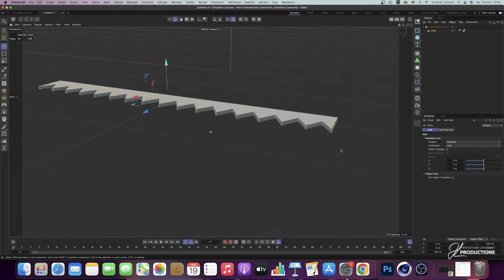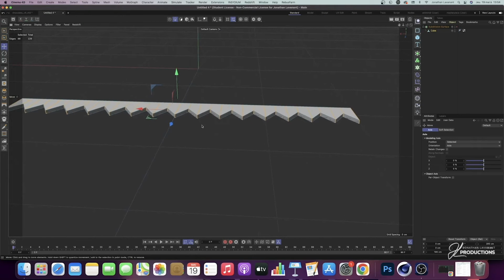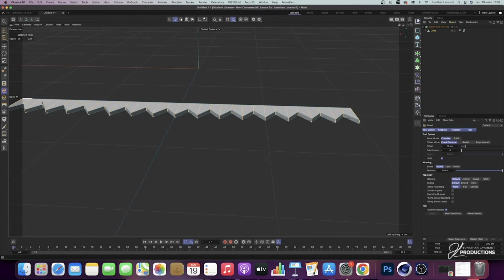And once we've done that, we'll be able to add the bevel to be able to add geometry and be able to keep fairly rough edges at the subdivision level. So it's right there in your left tools. There I left click, dragging with my mouse at the level of here. I will put 0.2. It will be more than enough.